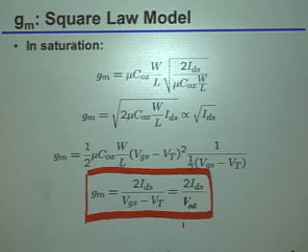The smaller you make that overdrive voltage, effectively the larger capacitive parasitics you're going to get for the same bias current, right? That is indeed true, and as you basically said, it's going to slow the devices down. We'll talk a whole lot more about that, but that basically says there's now an immediate obvious trade-off: I'd like the overdrive voltage to be small to get a good transconductance for the same unit current. But if I make it too small, my parasitics will be very, very large, and I won't be able to get any speed out of the device. That's certainly one very important trade-off. We'll talk about that more.